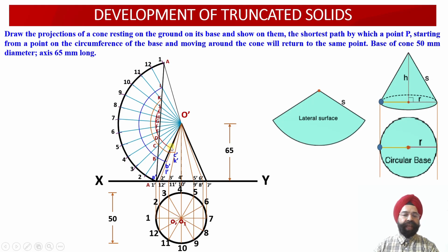Now from this true length, again we are going to draw a horizontal projector line onto the apparent lengths O-4' and O-10', so that 2 points of intersections D' and J' will be located onto O-4' and O-10' respectively over here. Now next couple of slant projectors into the front view projections, they happen to be O-5' and O-9'.